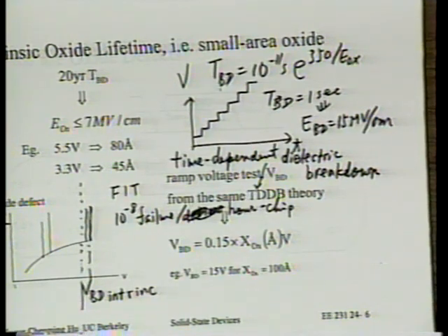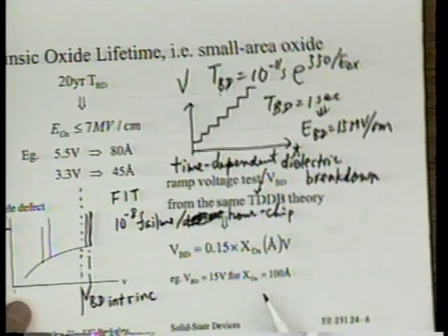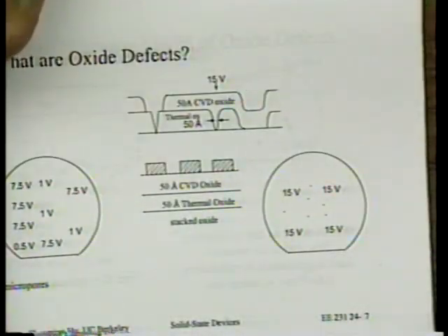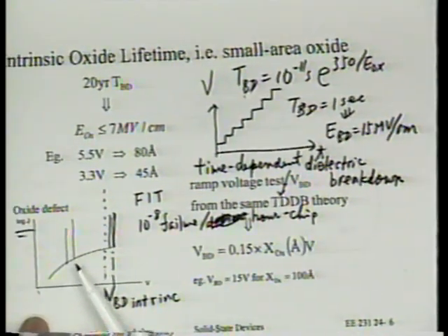Okay, it's that predictive. So there's no ifs and buts about this ramp breakdown either. Okay. Now next, what I'm going to do with this information? Remember, our goal is to relate this very simple breakdown test to lifetime. I think you may already see what I'm getting to now. So we're going to now try to figure out the actual effective thickness based on breakdown voltage. Okay, so in other words, we're going to try to interpret this lower breakdown voltage.